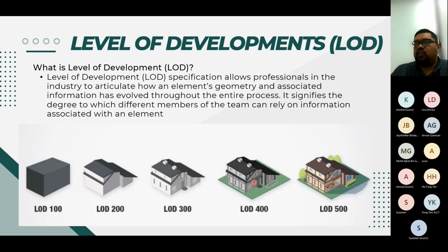But some of the projects use a definition that LOD 400 is the as-built. It depends on the requirement. But I find that a few developers use this clause that the LOD 400 is the as-built. So they will provide us the LOD 300, which means the consultant team will provide it. So we update to LOD 350, incorporate all the shop drawings from the trade contractors, and then finalize it in the LOD 400. So it depends on the requirement.